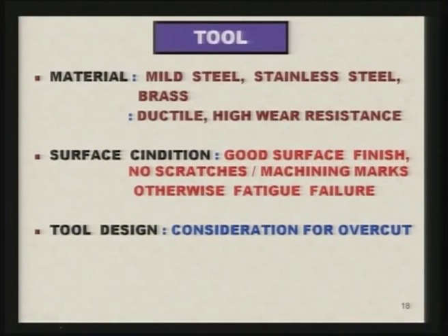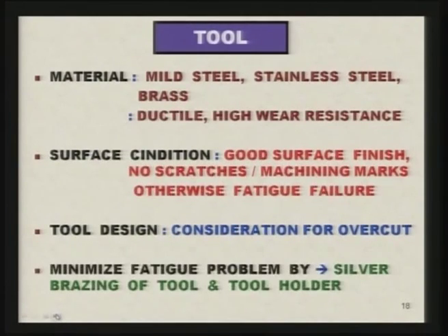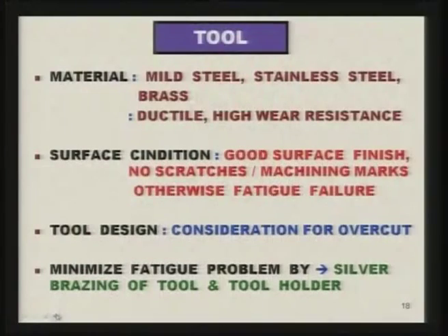Tool design consideration: overcut should be taken into consideration at the time of tool design, so that you get the desired shape and size of the machined workpiece. Minimize the fatigue problem by silver brazing of tool and tool holder. You can minimize the fatigue problems if the tool and tool holder are silver brazed.